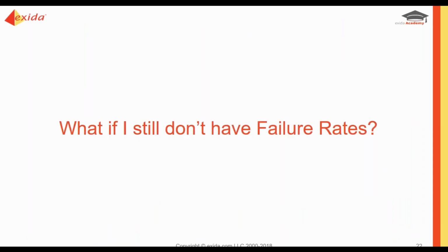So this is all well and good, and that might be great if you have certified products. You will have an FMEDA, and now you know failure rates from that FMEDA. But what if you don't have a certified product, or what if your components don't have FMEDA done? What if you are not in high demand mode, so you can't do cycle testing? Well, what do you do now? What if you still don't have failure rates? Well, this isn't the perfect answer.